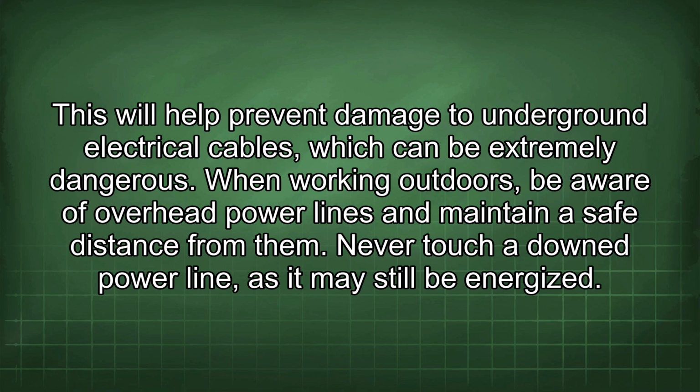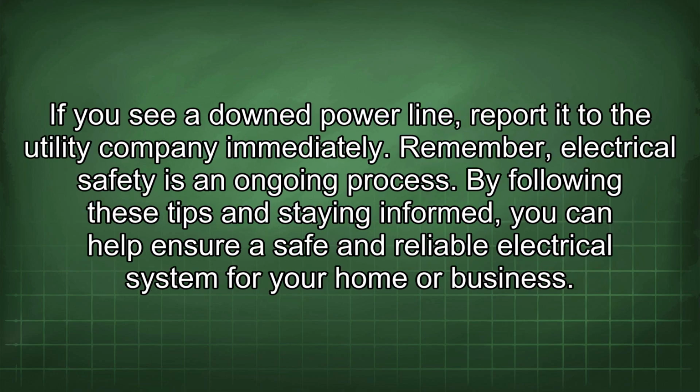When working outdoors, be aware of overhead power lines and maintain a safe distance from them. Never touch a downed power line, as it may still be energized. If you see a downed power line, report it to the utility company immediately. Remember, electrical safety is an ongoing process.